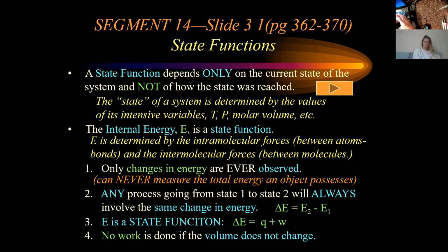By the way, that device is called a bomb calorimeter for a real good reason. The jacket and the lid is so strong and sturdy. It's usually about a 1/4 inch stainless steel. And you can carry out some pretty big explosions inside without it actually exploding. But it's put together on the top generally with good strong threads, and at the top of those, where the two pieces seal, it has a rubber O-ring, and you tighten it down and compress it so that O-ring seals it off, so it can't escape out around the O-ring, and you're good.